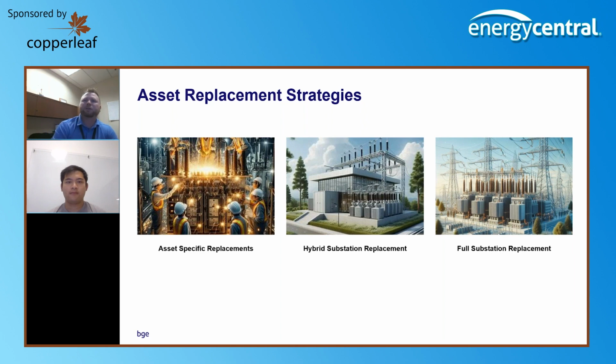And then I think the last one is pretty straightforward, but maybe not one that typically came out of a system performance or aging infrastructure budget in the past, which is to be able to evaluate, hey, everything in this station is old. If you go through and replace all the assets, you're still going to have potential grounding issues or control cable issues or control house issues, right, that need to be addressed, and you're going to spend capital. So if you bundled all of that together and looked holistically at the value of that compared to what it would take to do that, do you start to pencil out some projects that make sense?